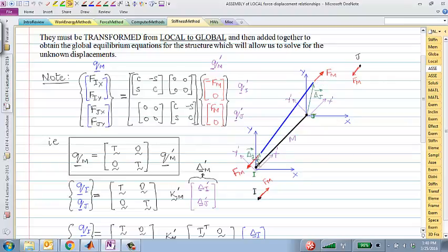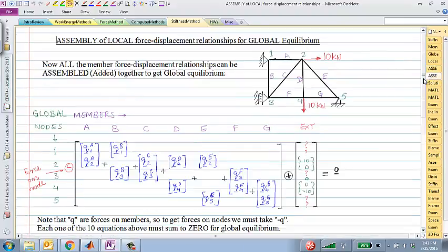The way that I've drawn it looks like it is going to cause tension in the member. But we are not summing forces for members. We are summing forces over the joints I, J, and all the 5 joints, or however many joints there are in the truss. The forces on the joints are actually pointing exactly opposite to the element forces. That's why we added this negative sign out here. So that's one thing to keep in mind.